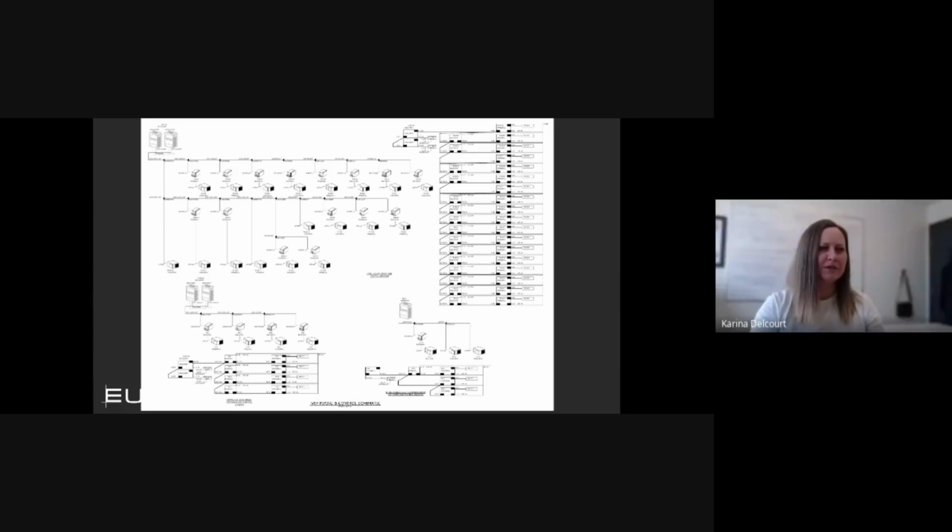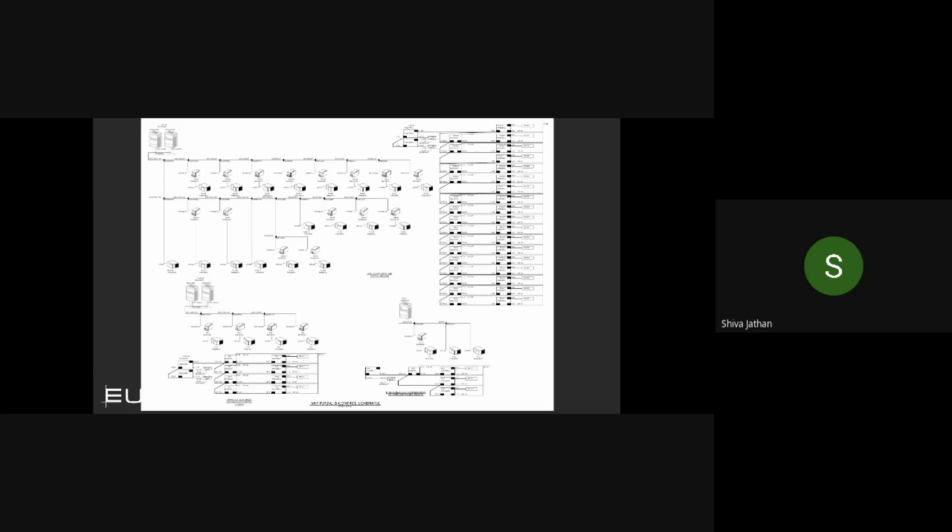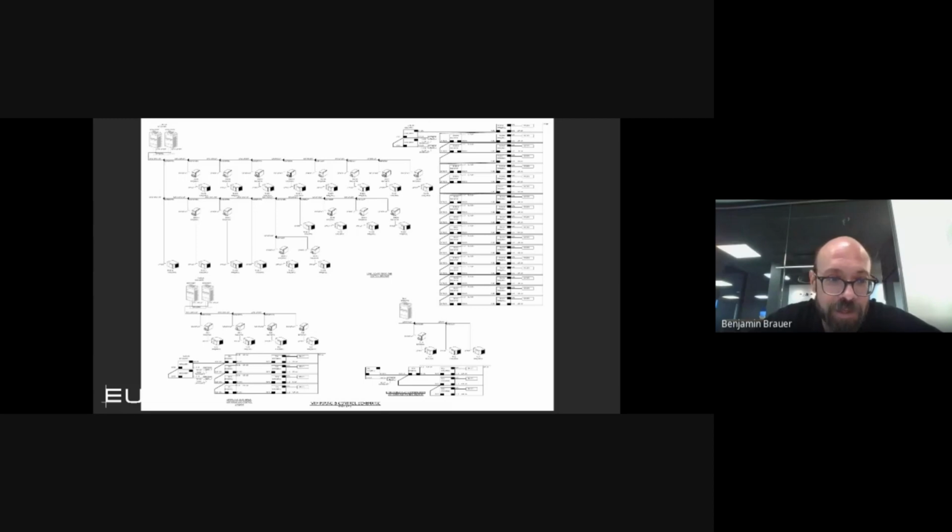If there are more questions, feel free to ask Ben. Go ahead, Shiva. Hi, Ben, thanks for the presentation. Would you say the FCU system is the best, with the downside being the cost? I'm always a huge advocate for fan coils. The energy efficiency is way up there. The operating costs are lower than VRF. It's the tried and true method. It's the tank of mechanical systems. Very little could go wrong with them. Controls are easier, and it's easier to modify for smarter building applications. Fan coils are definitely my preference in almost all instances.